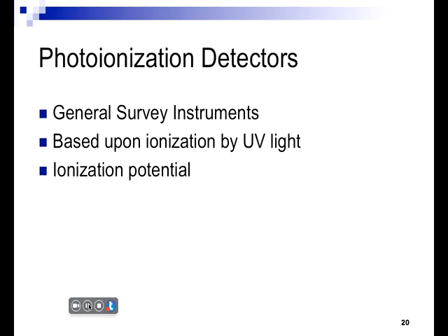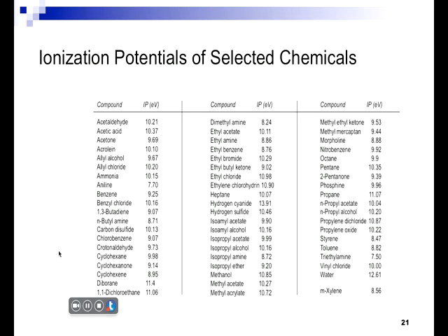And when you get into the X-ray range, you're clearly in that area. But before you get to the X-ray range, you go through your visible light range, and then you get into your ultraviolet light range. And somewhere in the ultraviolet light range, you get a portion of the ultraviolet spectrum where you have enough energy to create ion pairs. And that's what gives you sunburn if you go outside a lot, or you can use that technology to create ion pairs and measure different types of gases and vapors, because what you're measuring is ion pairs. Because every gas and vapor has what's called an ionization potential. And that's how much energy you have to hit it with to make it into a plus charge and a minus charge. And if you can do that, you can measure it. So that's kind of the technology that it's based on.